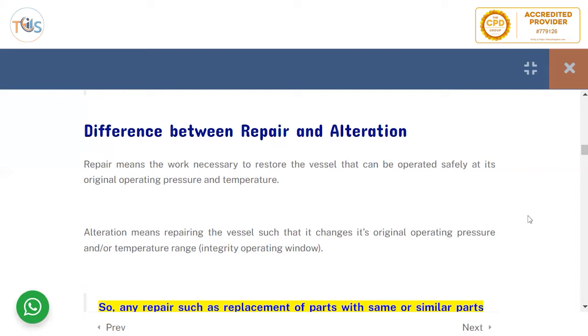Then you take some of the thickness reserved for the design pressure, but you have to bring down the working pressure so that not as much thickness is needed as originally intended. Part of that thickness was reserved for design; by bringing the pressure down, you use it for corrosion allowance, if you know the corrosion rate. So that's called derating.